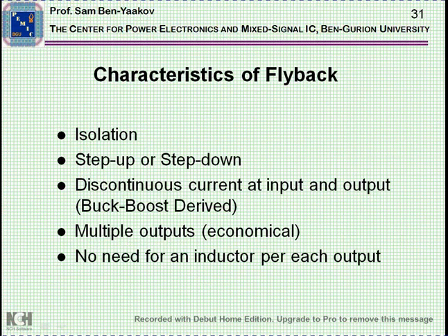Okay, let me just sum up what the characteristics of a Flyback converter are and why it is so useful. First of all, we have isolation, excellent for offline applications. We have this capability of step up or step down. We can have a higher voltage or a lower voltage, as needed in a particular application.